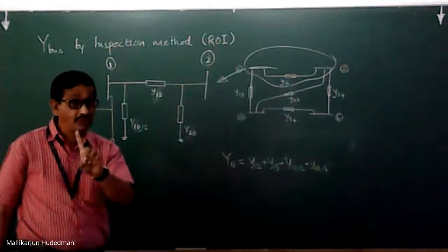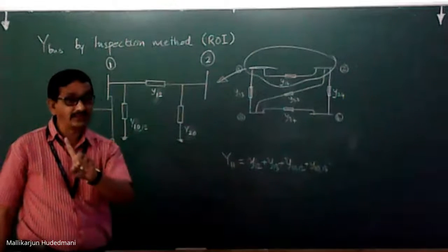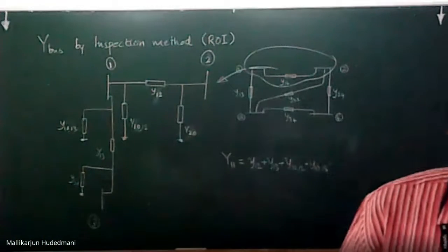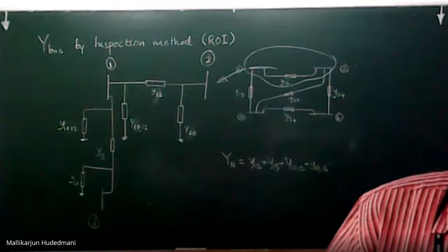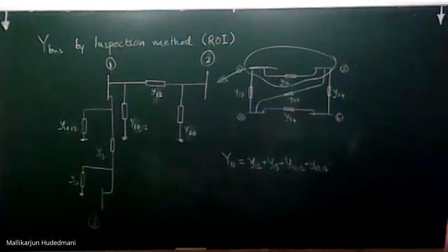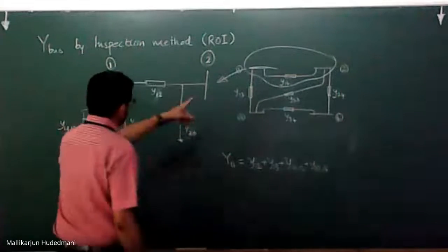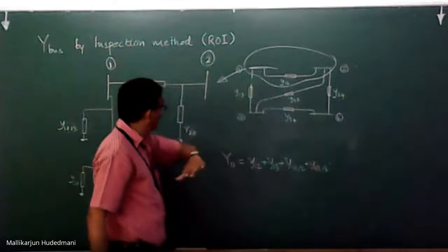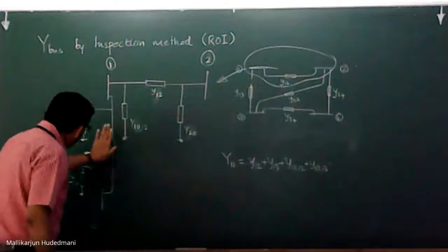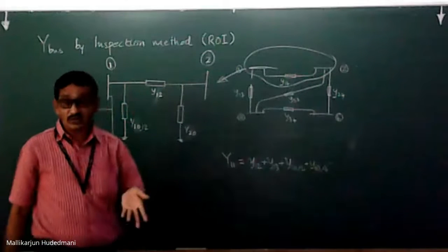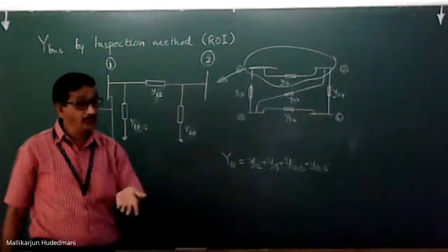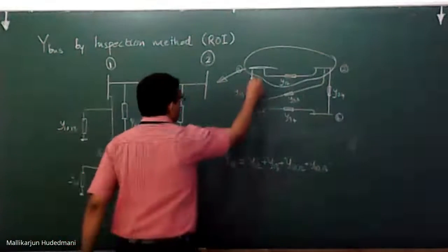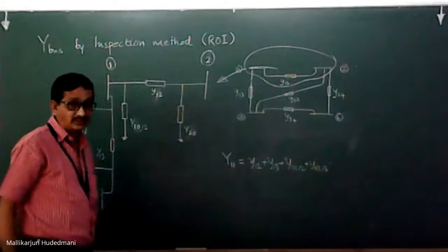This is true if you add a line or delete a line. Your modification to the Y bus shall go in the computer. You have to devise a program or write an algorithm that keeps tracking. This may be due to a fault. Imagine a new line is connected between 1 and 3, or there occurs a fault. Line is broken. If line is broken, it means isolated. This structure needs to be deleted from the calculation. So you must have an algorithm or a computer program which is able to understand and get your need for that. Therefore, the mathematical representation works very necessarily.